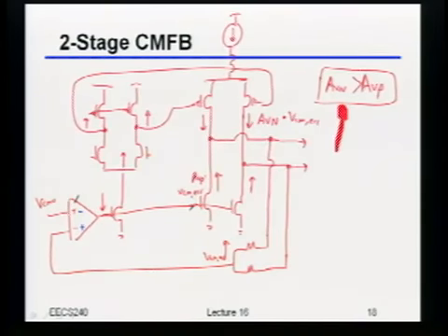Okay? Yeah. So if you add in the current source, you eat into the swing. That's true. So no free lunch, right? You're going to eat into the swing. So indeed, you may actually just want to do the thing we had discussed before, which is separate the common mode feedback for the two stages. It's a good question. Any other questions on this?